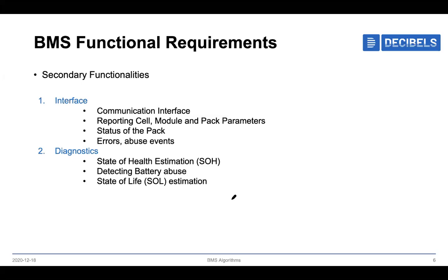So this interface should report all cell faults, or the problems in the cell, module level, and also pack level. It also has to show the status of the pack in terms of SOC, state of health, and state of energy. At present, most of the BMS represent the state of charge but not state of health.